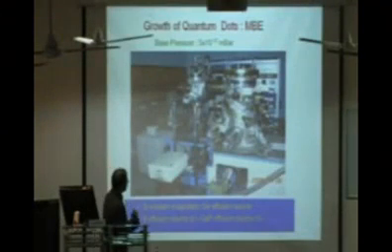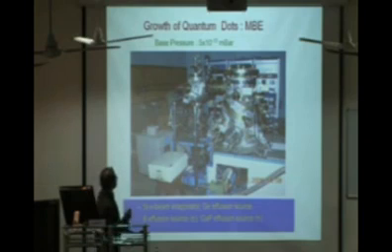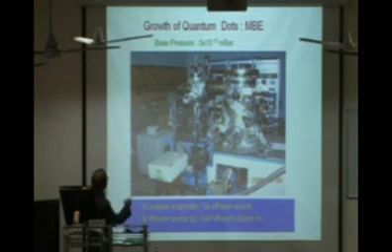Those are more stable. In fact, what we grow in our Kharagpur lab is done with something called molecular beam epitaxy. This is a very old system we have, about 20 years old. This is where you put the semiconductor growth materials, like silicon and germanium, in different sources, and all this takes place at a very high vacuum, about 5 times 10 to the minus 10 torr or millibar, which is the typical pressure. Here you put our sample, load the sample from here to here without breaking the vacuum, and then we grow the materials.